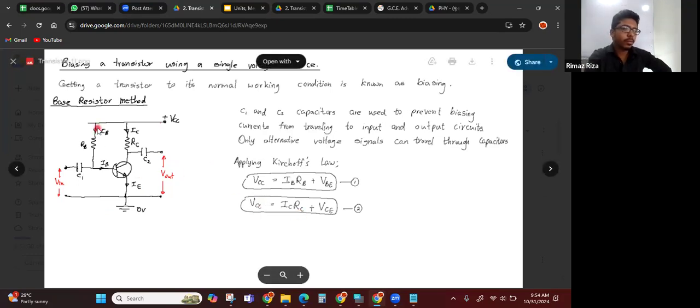So here VCC, a voltage here drops across this resistor and across this barrier voltage. And here we can consider 0 here, so it's ground, or otherwise it's relative to here. So VCC equals IBRB plus VBE, and then ICRC plus VCE, potential relative.